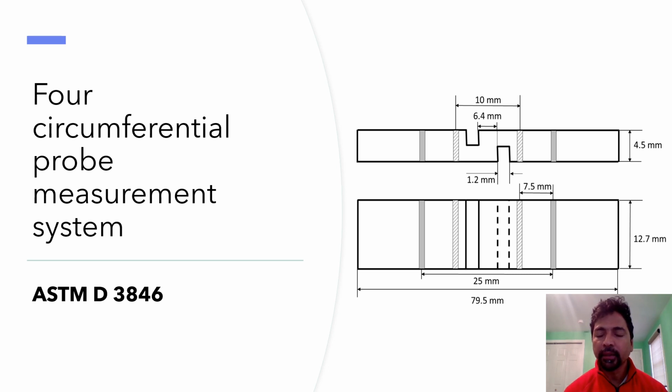So when we have a shear deformation, we anticipate seeing damage, interlaminar shear damage, within the composite, and this damage can change the resistance of the composite. So for a given applied load, we should be able to measure the change in resistance through the measurement of change in voltage between these 2 slots, which are under shear deformation.